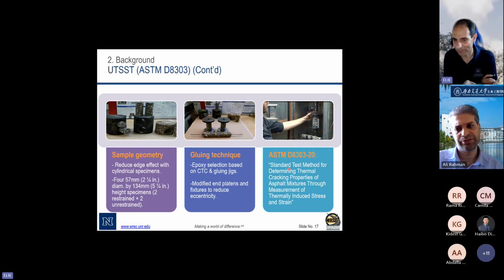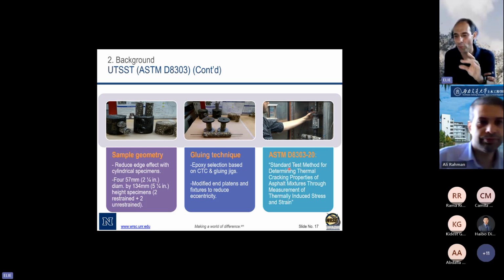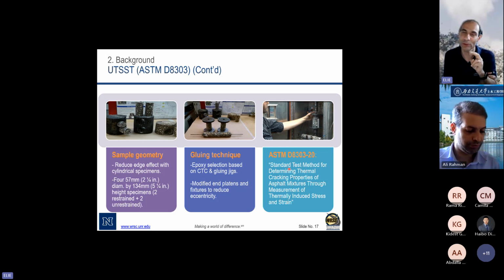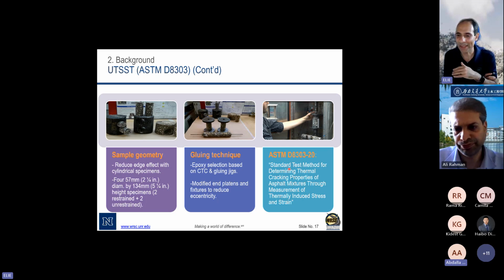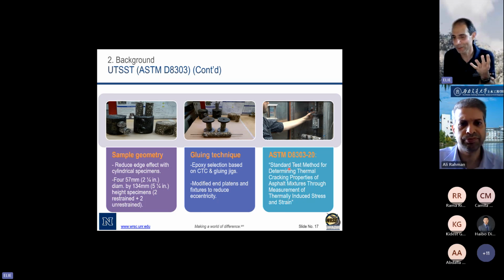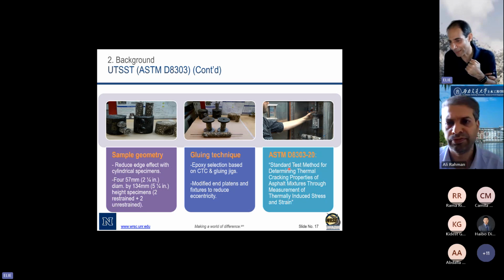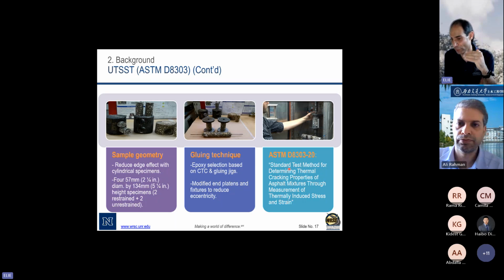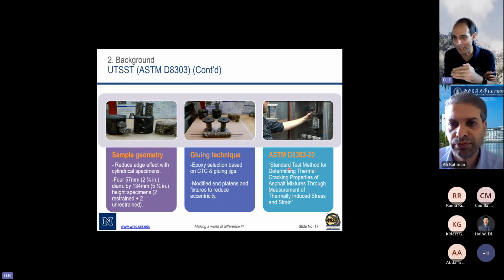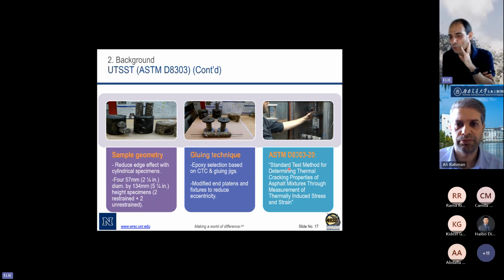the entire depth. So what they end up doing is dividing that into four layers, let's call them sub-layers. That way it takes four cycles to crack the entire layer, which means, let's say, four years. But then, based on the probability and the amount of cracking on the surface, you can only reach 50% of the depth. And that's what explains your two years over here.